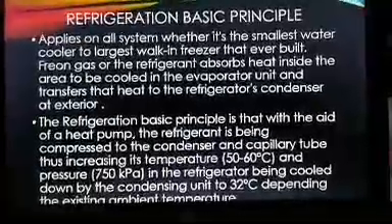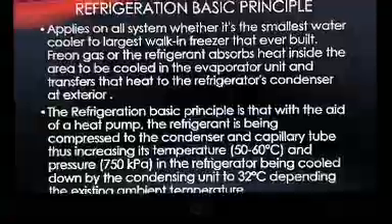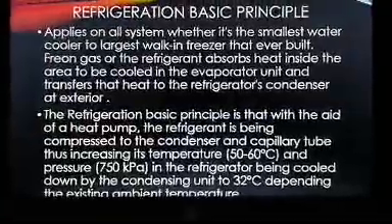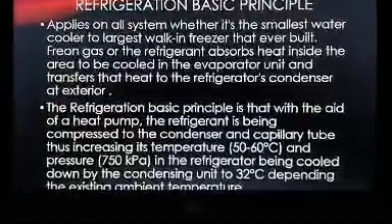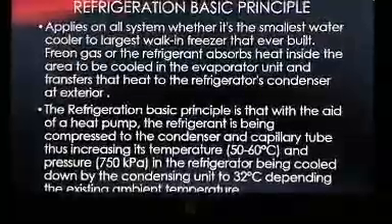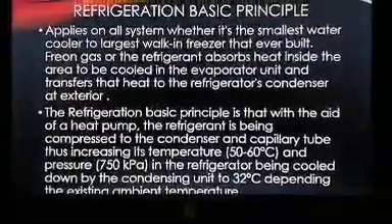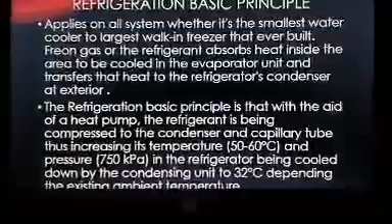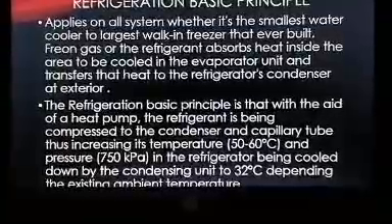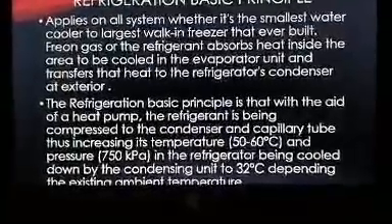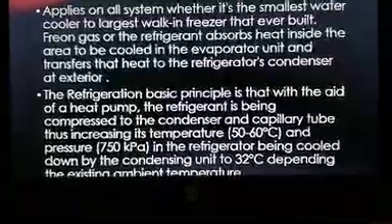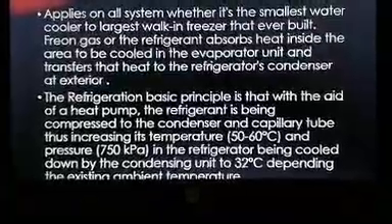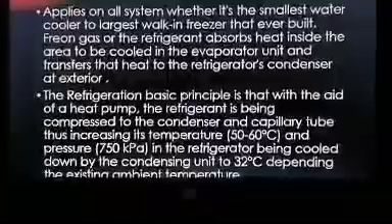Refrigeration basic principle applies on all systems, whether it's the smallest water cooler to the largest walk-in freezer ever built. Freon gas or the refrigerant absorbs heat inside the areas to be cooled in the evaporator unit and transfers that heat to the refrigerator condenser at the exterior.